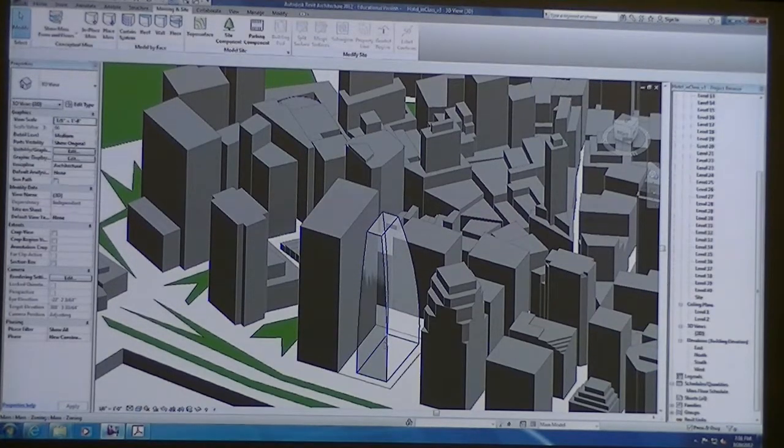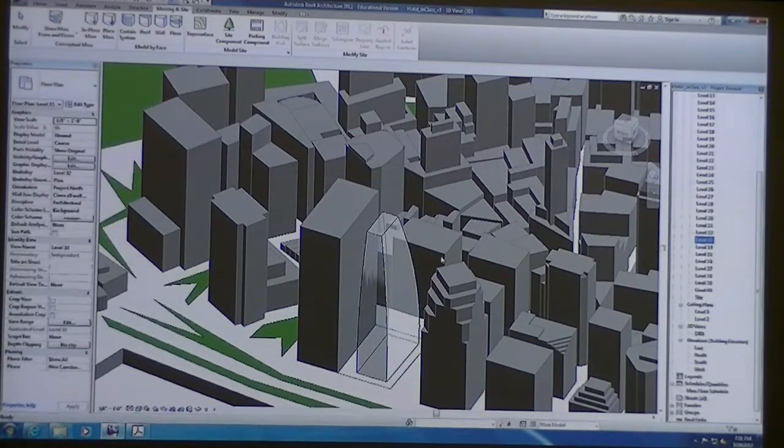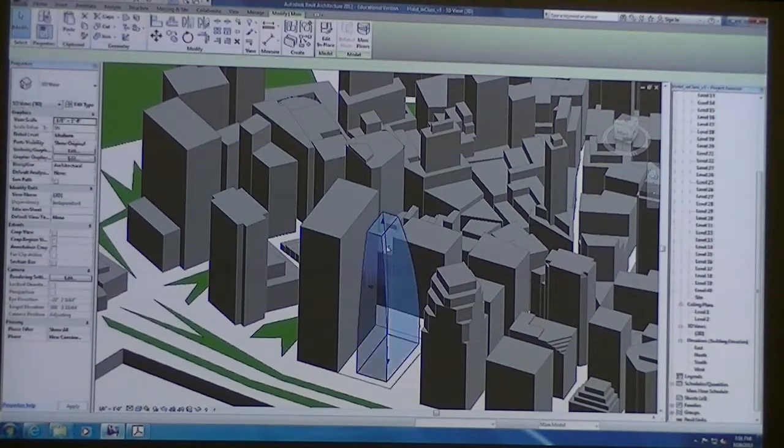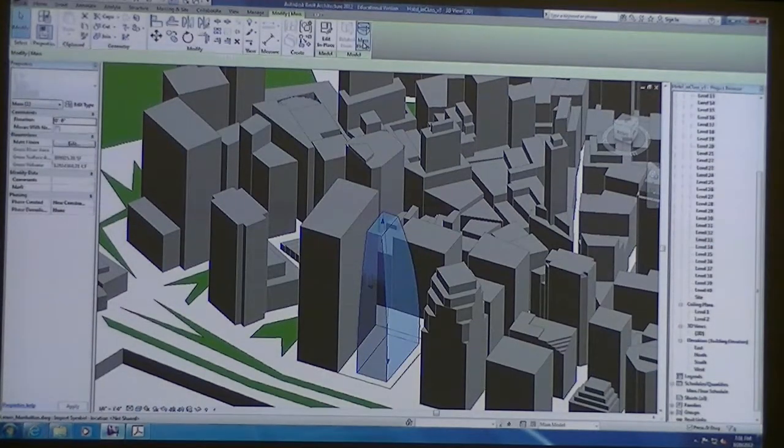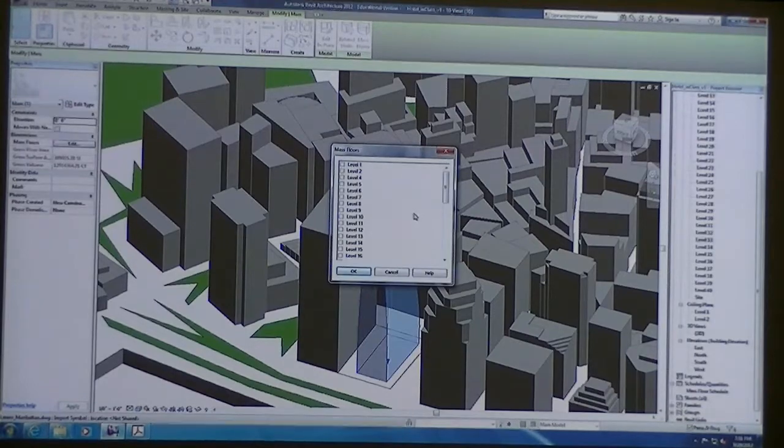And if you want something to be as tall as this mass, that means you might have kind of a tall, skinny tower in order to get all the way up there. And of course, you don't have to have a mass floor on every single level. You could skip a floor. So if I were to select this mass, and let's just pretend this is your hotel, I could have selected, let's say, levels 5 through 40, and then maybe I only select level 1.